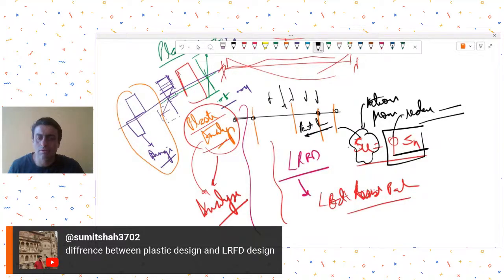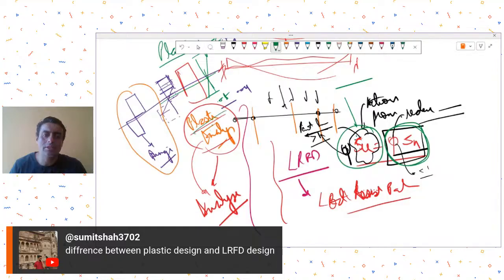Here we will multiply the actions by some omega, which is the partial safety factor for loads. This value will typically be more than 1, and the reduction factor for materials will be less than 1. Finally our aim is to provide strength in the section which is more than the actions. These actions can be derived using elastic analysis or plastic analysis also.